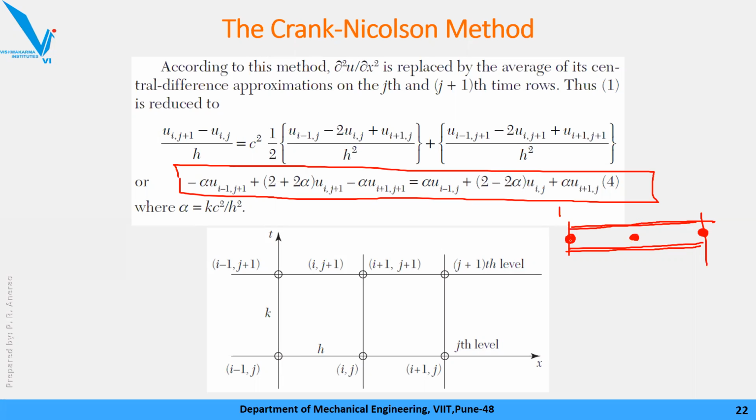For the sake of simplicity we'll take only 3 locations, because we have implemented the finite difference approach. Whatever bar there is, we have broken it into pieces. We have created a grid. As this is 1D only, only one grid is formed, like this. Node number 1, node number 2, node number 3. Instead of numbering these, I'll say this is the left hand node, this is the central node, and this one is the right hand node.